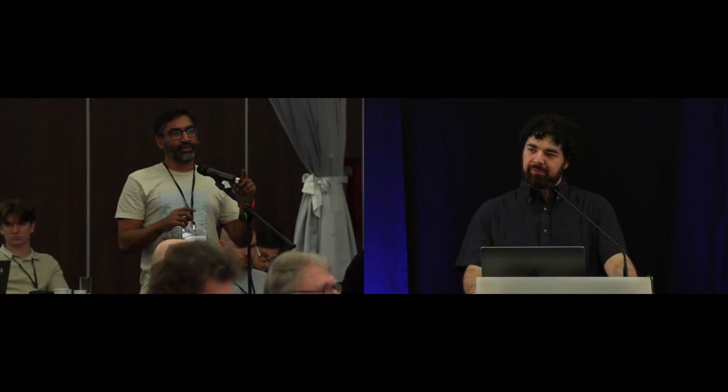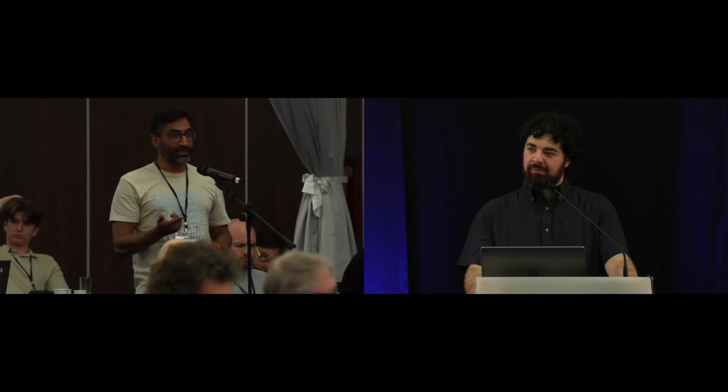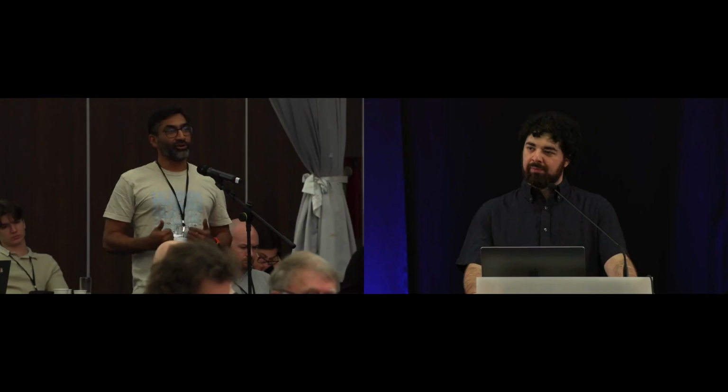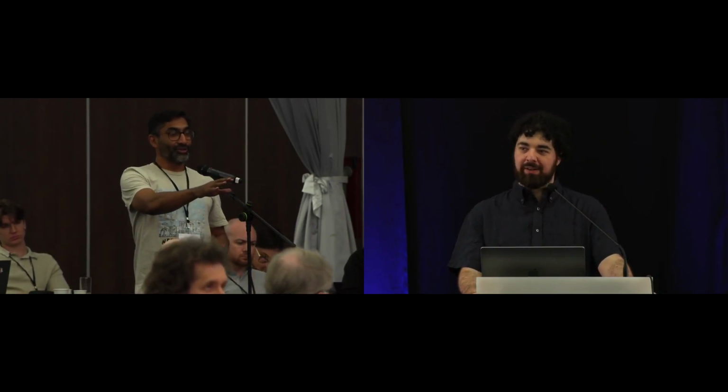I'll just add to PJ's comment. I think that's a very important thing, right? If I'm integrating a PHY, I get to decide in my silicon how I'm going to even expose it to you. Is it an NB-IO bus? Is it a direct map register? That's my call, right? If I'm taking some vendor's PHY and plugging it in, there is no requirement today on me to give you even an interface. That is partially why I was thinking of making this very abstract and make it Ethernet, to say, going to the vendors, you figure out how you're accessing this information. We're just providing the user interface through.